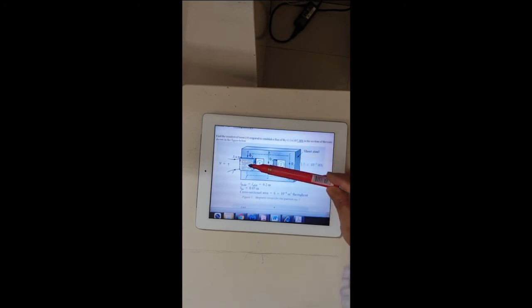The primary side is wound by N turns, and there is a slot between this core, one slot here, another one here. Due to this winding, the flux lines are produced and flow through these paths. The total flux phi t divides into 2 parts, phi 1 and phi 2, and they come together and join again as phi t. It's like the total current dividing into 2 parts.